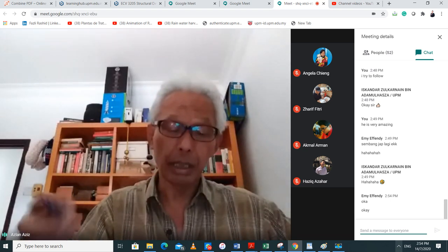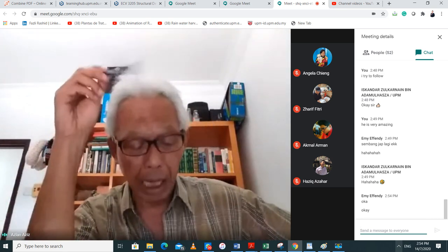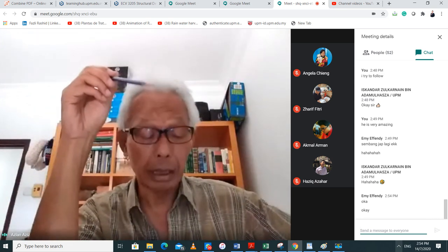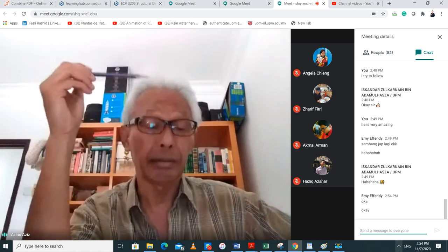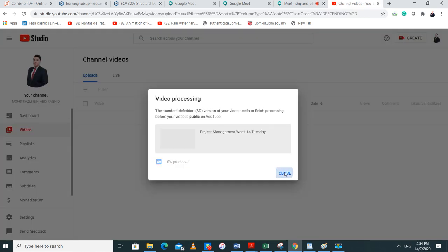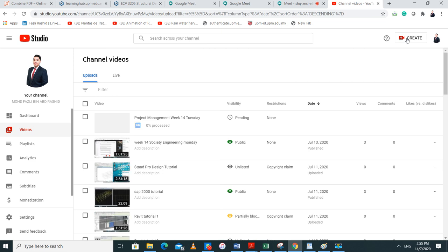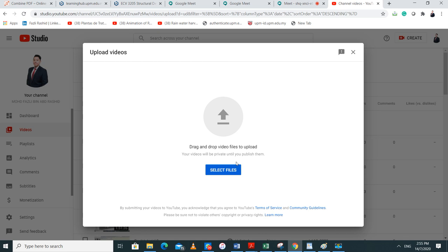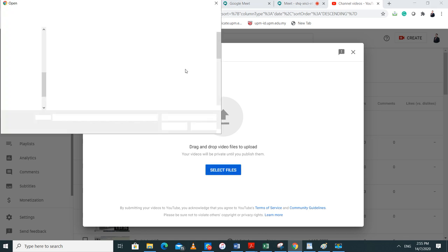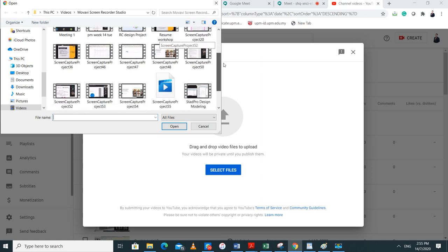So the diagram there shows that I have my pile, okay? Pile is in soft clay and in dense sand. A few minutes ago when we were doing that CPT, we said to ourselves, it would be great to have the pile in the dense sand or in stiff clay, because this would give us a higher bearing capacity, all right? So we stick it into the dense sand, and then we notice that there is a soft clay above this dense sand from the site investigation.